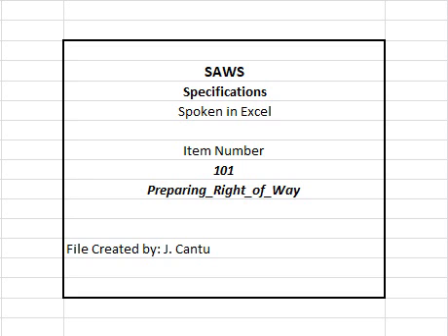7. Areas to be used as borrow sites and material sources shall have all obstruction, objectionable materials, vegetation, etc., removed to the complete extent necessary to prevent such objectionable matter from becoming mixed with the material to be used in the construction.